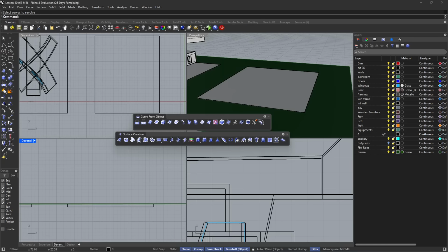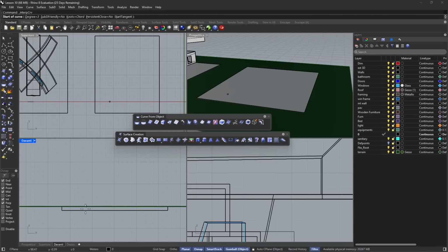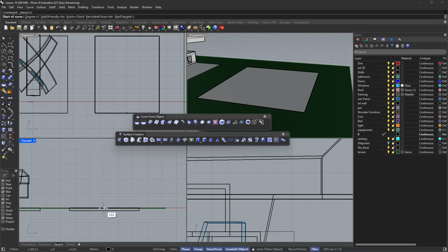So I'm going to create a curve. I'm just going to create an interpolation spline. Let's say that this is the midpoint of this platform, let's project here. So this is going to be the axis of this revolution. So if I do something like this and I don't come back on this axis, I stop before, it's going to leave a gap in there.